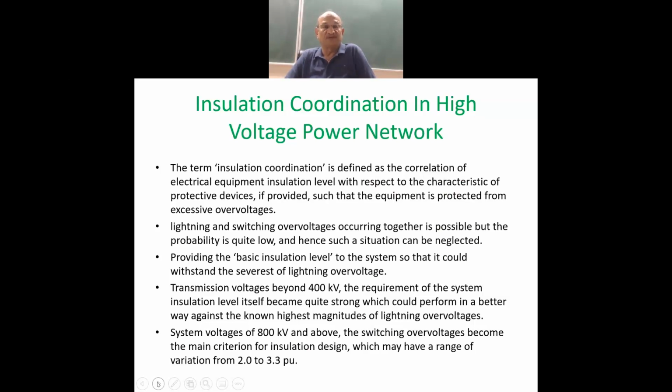That is what we have also learned, the basic insulation level of the transformers. Later, the concept of the switching impulse level of the transformer had to be designed. If you designed for the highest transient overvoltage, you may have to provide a very high level of insulation. That means higher cost for the equipment, for the transformers.